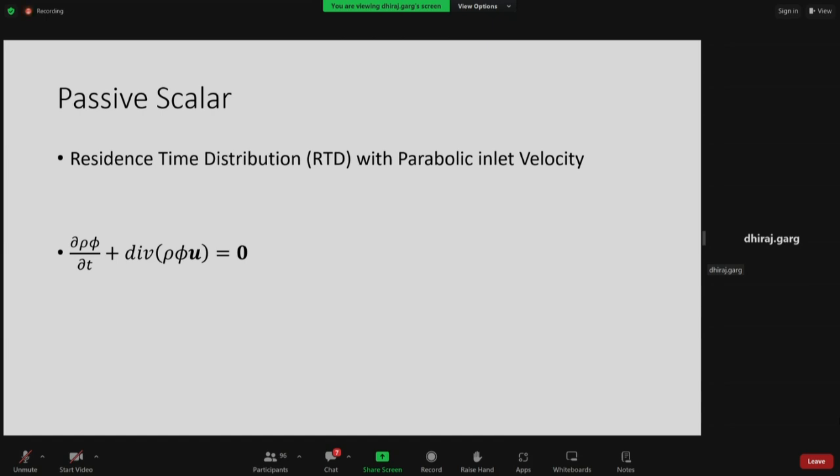So when the system solves, it will not solve for pressure and velocity because it is already solved, and it is not affected by the injection of phi, because phi is a passive scalar. Had phi not been a passive scalar, it would affect your local velocity and so your pressure calculation again. Okay, sir. So you do not need to worry about pressure and velocity. Since they are already there, you are only looking at the injection of the tracer, and it is only solving for phi.